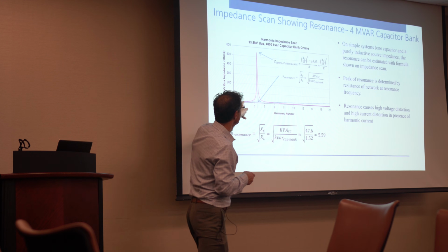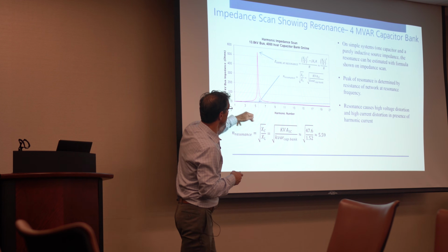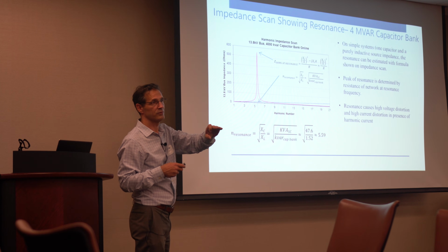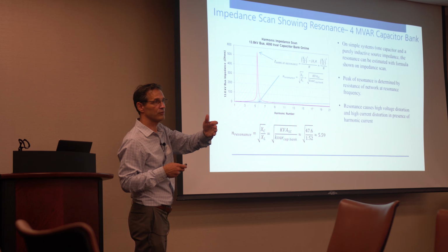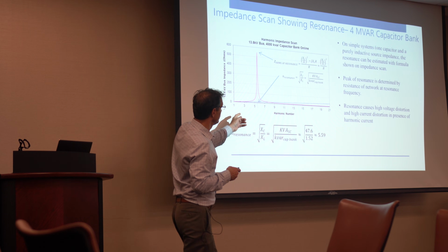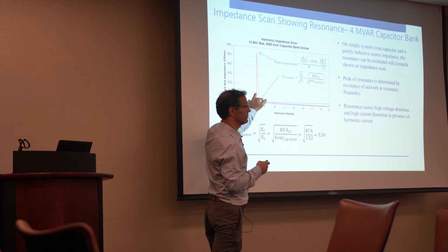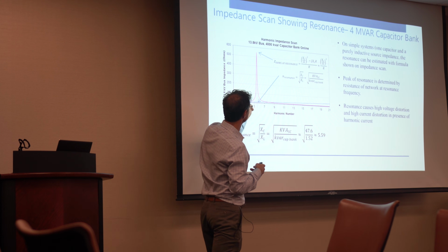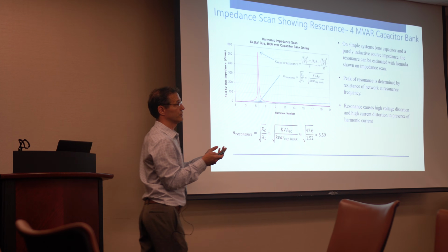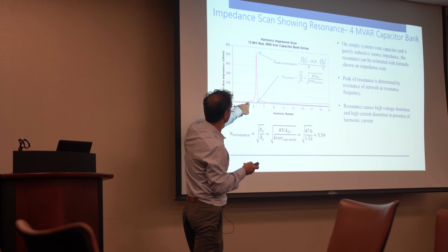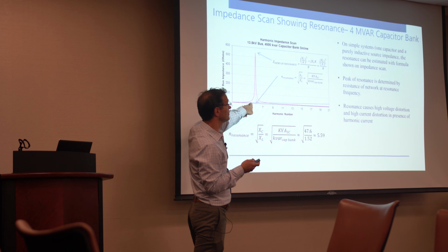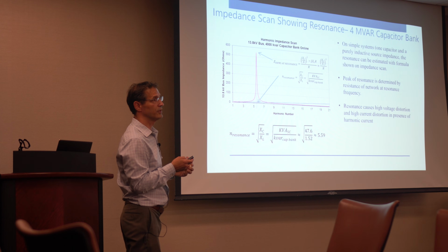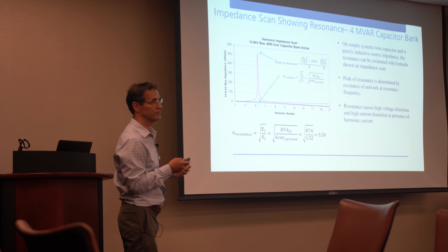So you get this magenta curve. This blue line here represents the impedance of the transformer, right? That same impedance curve. So you can see that for a current injection, we are dealing with a much larger impedance now, right? At all these frequencies. We've gone from values that were, remember, 7.5 ohms at the fifth to being something on the order of 400 to 500 ohms potentially at the fifth. It can be very significant.